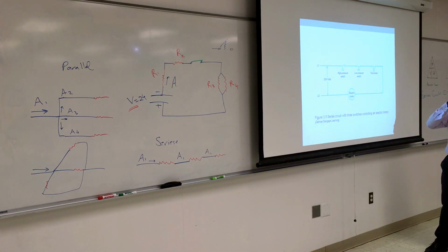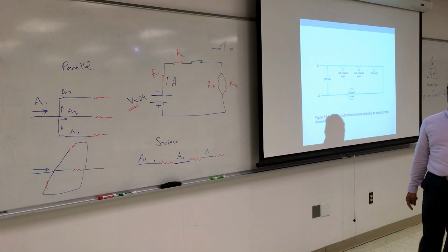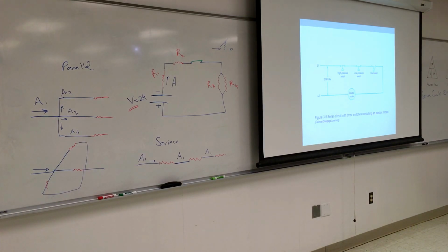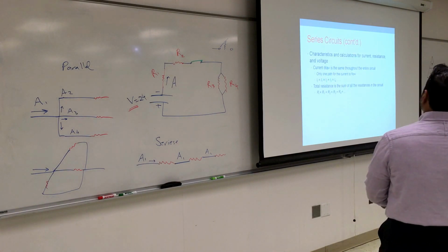It doesn't tell you much, but basically, we'll talk about thermostat. So these are all control switches: high pressure, low pressure, thermostat. Sometimes a timer can also be controlled as a switch. So all these are wired in series as control for the small circuit.